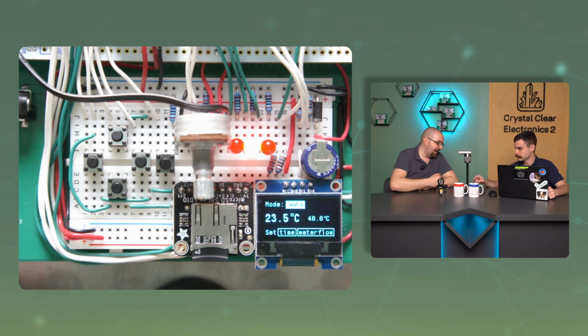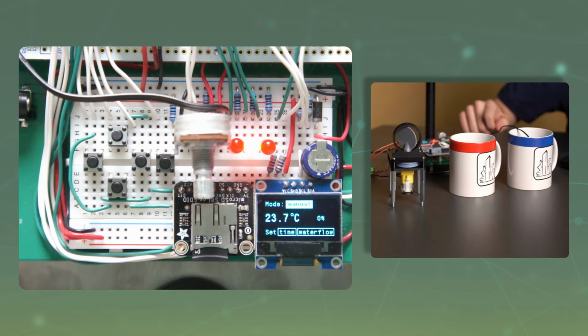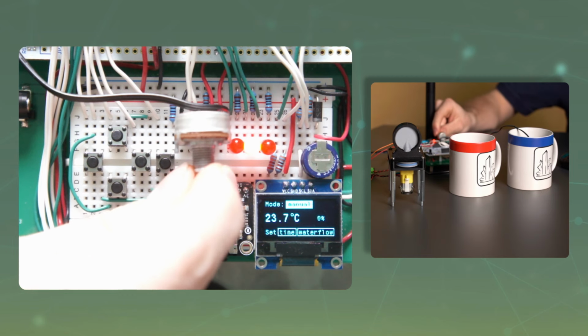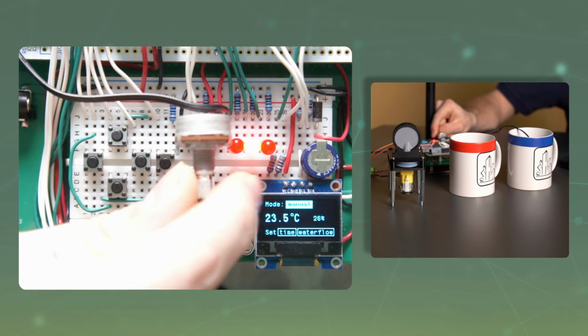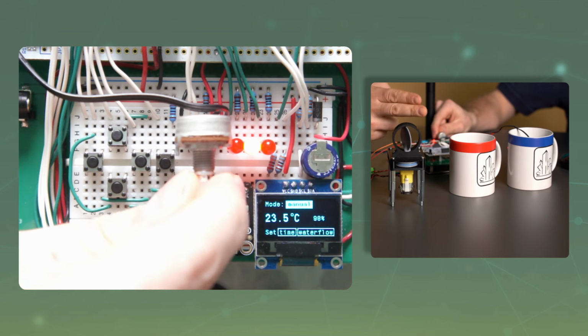But let's not start with testing the automatic mode, but with the manual mode. Because then, we can see the two control loops working one by one. We can see right away that the valve has turned to the 0 degrees position because the potentiometer is seemingly on 0%. If we start turning the potmeter, you expect the valve to move to the correct position. At 50%, we saw roughly a 45 degree angle.